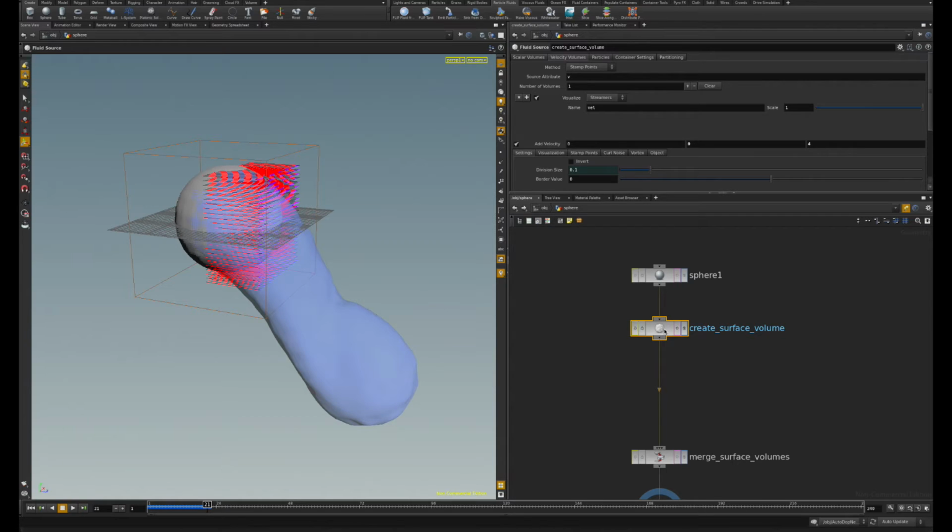To do that, we have to change a few things within our emitting geometry. This Cd attribute is stored on points in Houdini, and it is actually being read by the viewport. So if any mesh has a Cd attribute associated with its points, the viewport is going to display it in that color, and the renderer Mantra is also going to use that color.